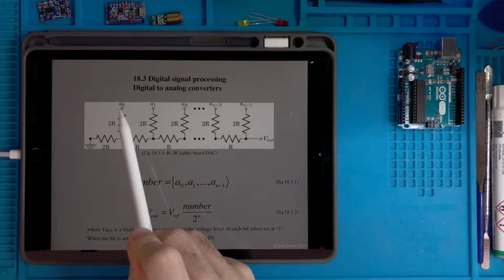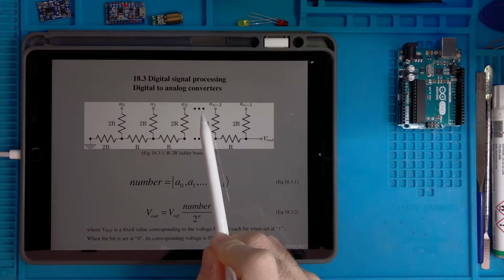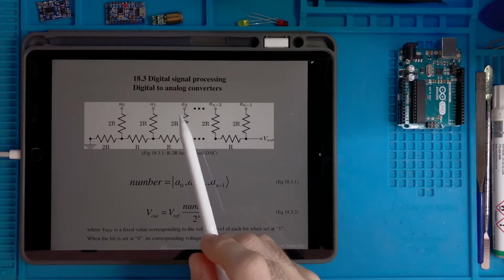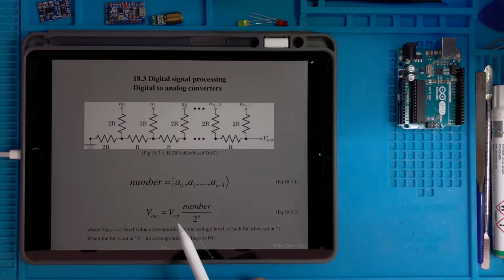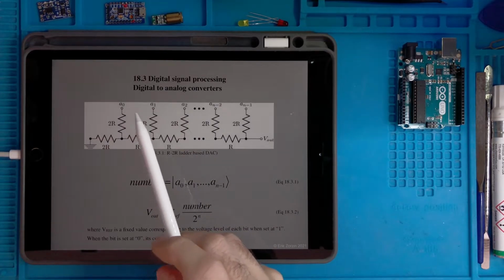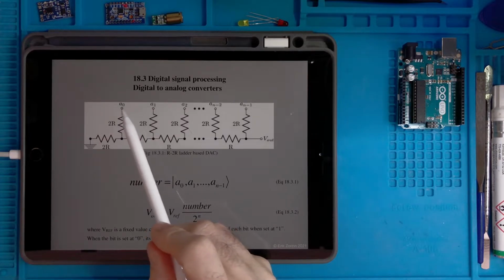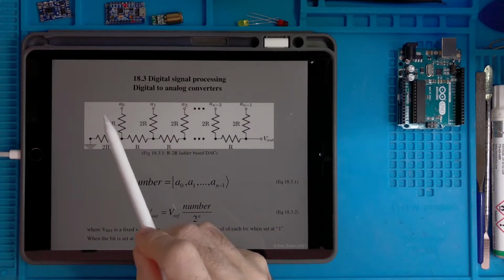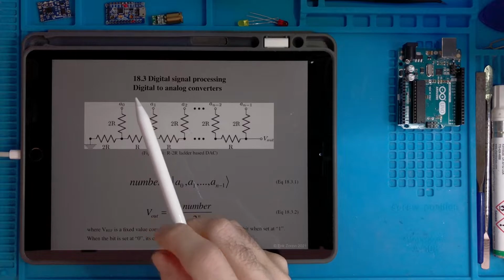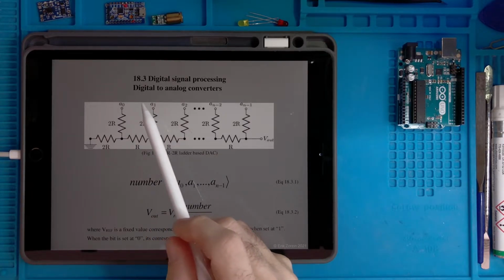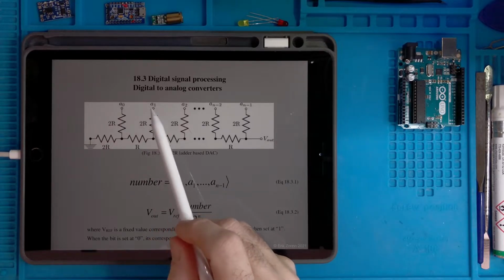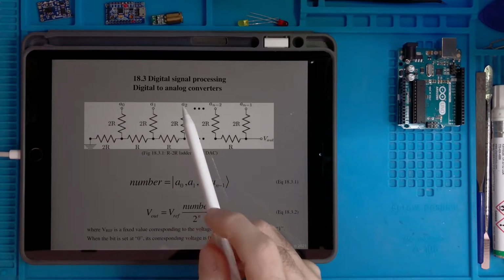So what do we connect here at the A inputs? We connect another source of voltage we call reference voltage, Vref, and the logic is that we can associate a 0 when this Vref voltage is not connected, or to better say, when this node or this or this or this are connected to ground, and we associate a logic 1 when we connect these inputs to the Vref source.